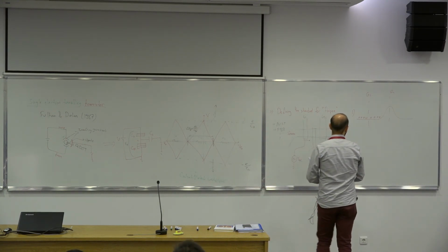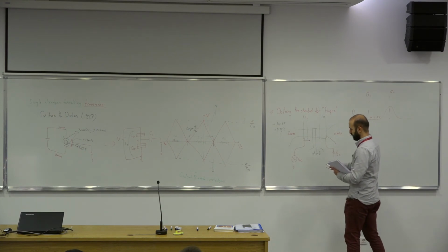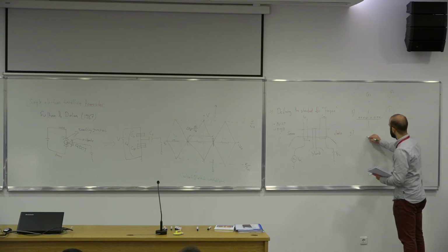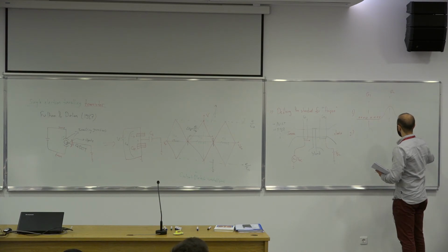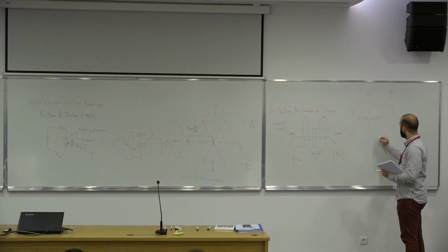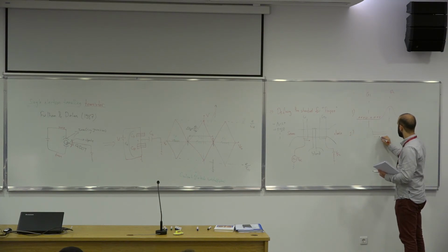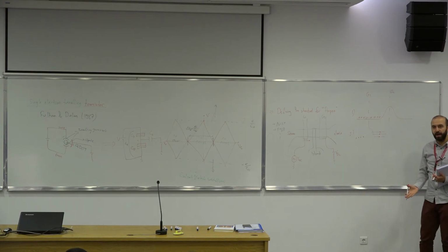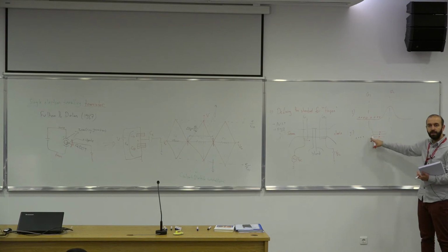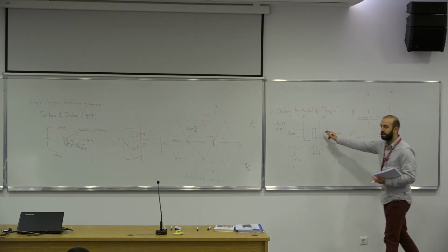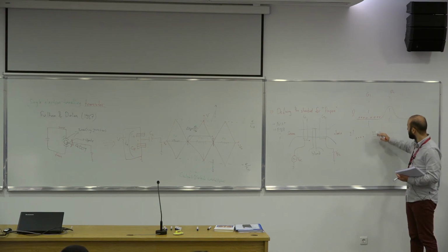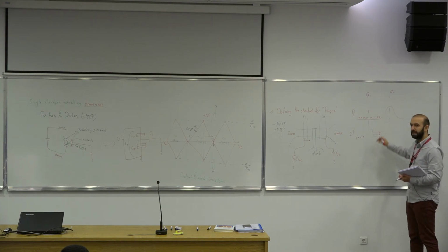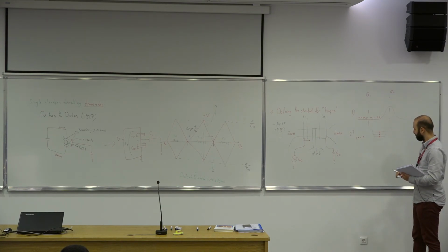in the next step, this is what happens. Since we are modulating the bias, the G1 will start increasing, which will confine the electrons. So these were pretty much free electrons. But now by increasing the bias on G1, you created a quantum dot here, which discretizes the energies, and then electrons need to reconfigure themselves so that they can fill up these discrete energy levels.